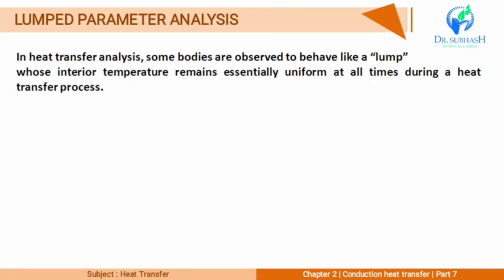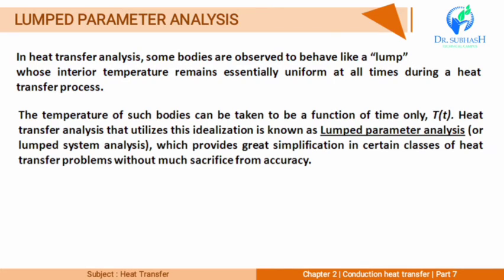Let's move to our next topic, lump parameter analysis. In heat transfer analysis, some bodies are observed to behave like a lump, whose interior temperature remains essentially uniform at all times during a heat transfer process. The temperature of such bodies can be taken to be a function of time only. Heat transfer analysis that utilizes this idealization is known as lump parameter analysis, or lump system analysis, which provides great simplification in certain classes of heat transfer problems without much sacrifice in accuracy.